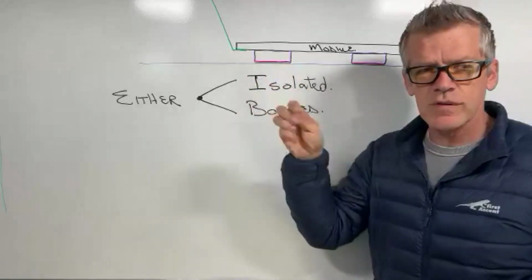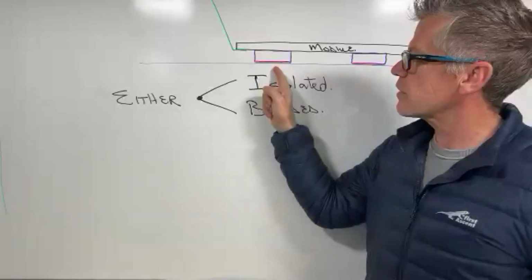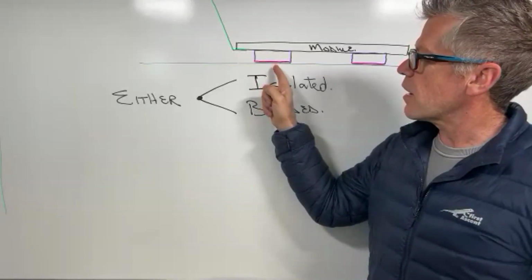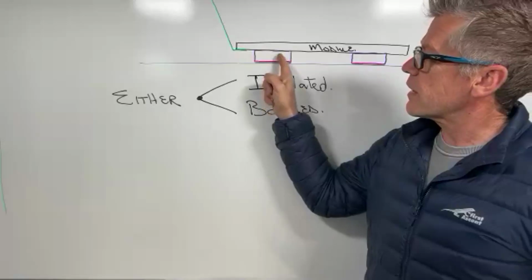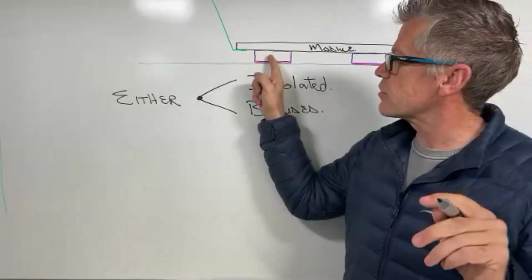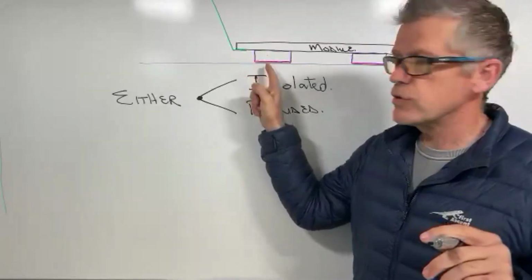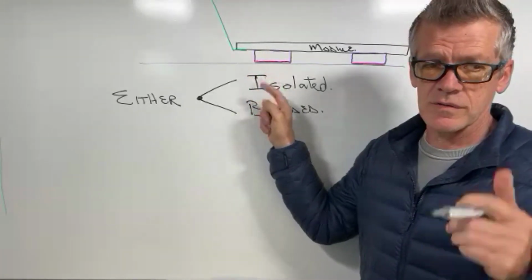The red over here was an insulating rubber in between the mounting structure and the IBR roof sheet. Now that is obviously the part that you were talking about that is going to create the fact that there's no continuity between these two metals, right?